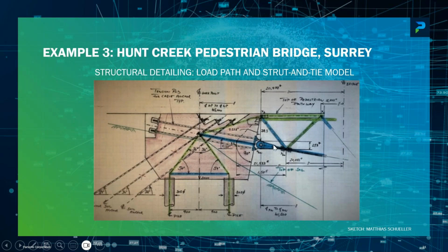Now, how is this structure built? First you install the cables that are actually 2 truss cords. So this is, if you want, 2 bottom cords, but each bottom cord has 2 cables for redundancy reasons, and it would even allow changing one suspension cable at a time while you still have live load on the bridge, because you can lower this cable and let it come down and then pull another cable in. The other cable would keep the bridge up. And this hasn't been done by any means for a suspension bridge yet. So you see how you can develop a performance of the structure that is new.